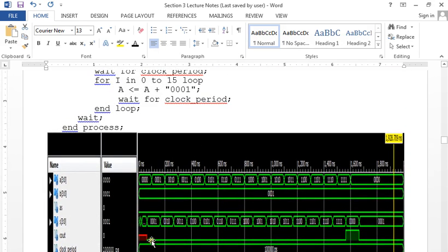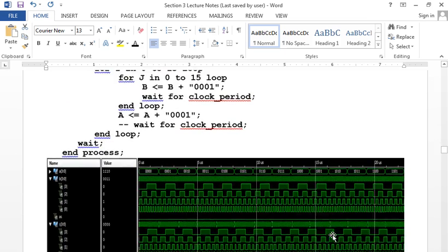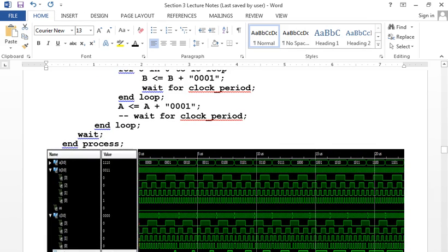So what happens is you see how you add 1 here, so B is just equal to 1, and then A is counting. And you see after the delay of 65 nanoseconds, it's just added, right? And then you get 1, 1, it becomes 0, 0, 0, 0, like we said before, but now you get a carry bit. And then it restarts again. So now we're down to 0, 0, and 0, 1, so the carry bit goes away. So it's properly simulated. Here I added the B inside the loop to show you what happens. So now we get carry out, but now the carry outs go longer and longer because we're covering more and more.